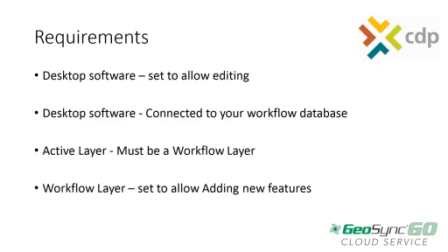And then also the workflow layer has to be set to allow adding new features. So workflow layers can be set up for read-only to limit editing. So you've got to make sure that that workflow layer is set to allow add features. And if those requirements are met, then you can create new point data.